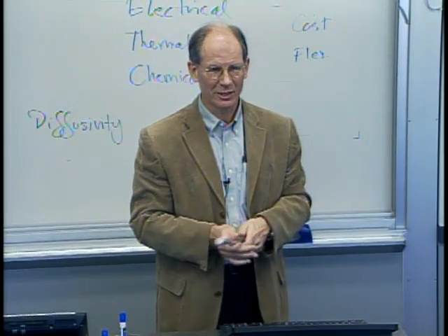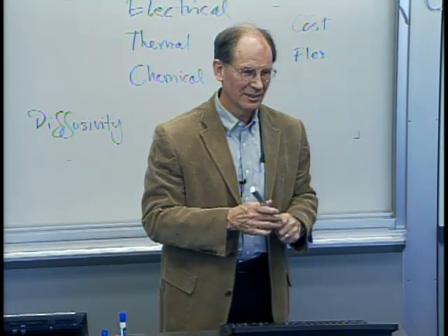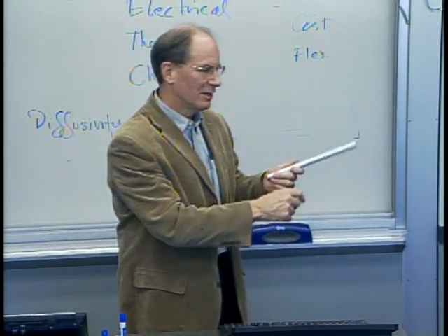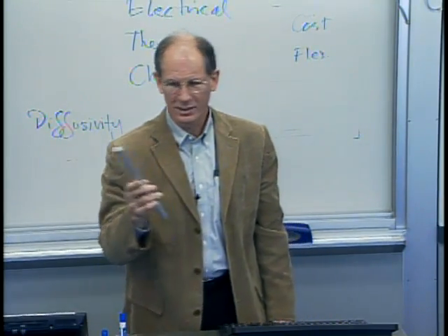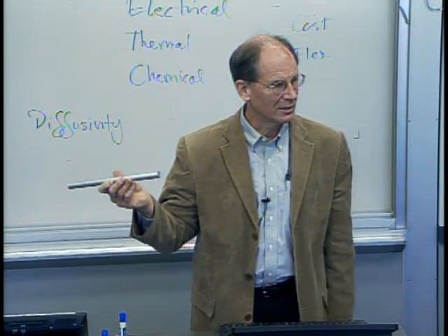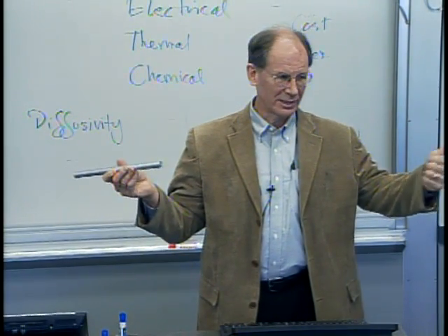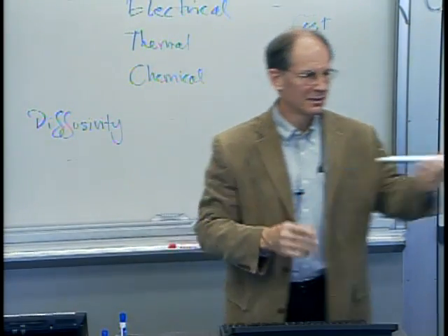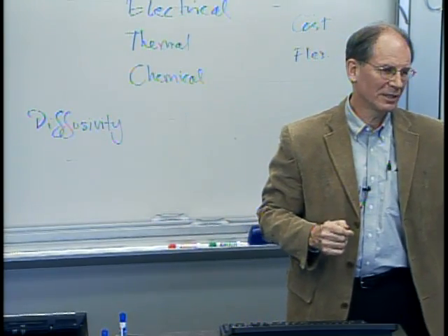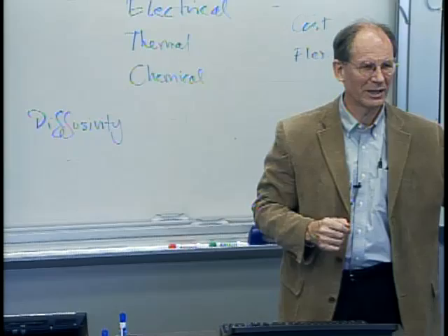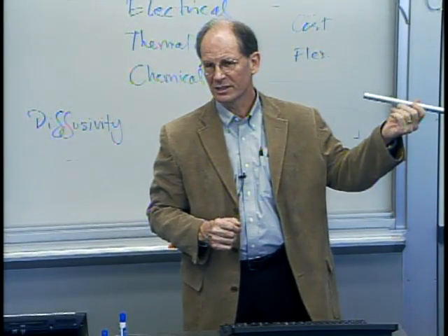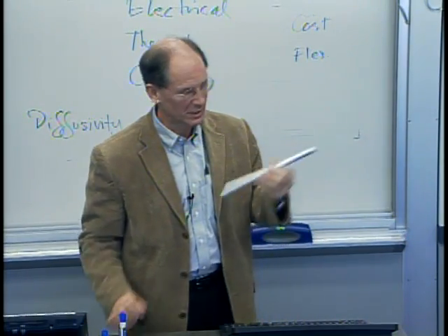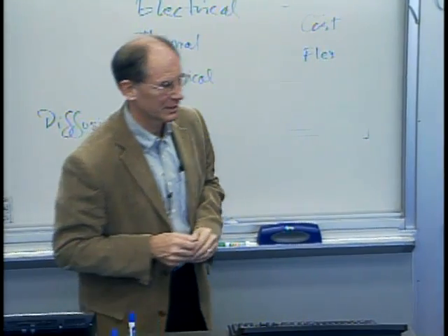Sure, if I put a different alloy in, or I sneak in steel or titanium instead of aluminum, yeah, that's a big mess up. But if I just say, well, here's a piece of aluminum, we did it in this mill over here, and it came out with the following properties: its elasticity, its yield strength, its strain hardening characteristics. And then I get supposedly the same material from a different mill, and they're 10% different. Not the elasticity, by the way, but all the others. 10% different. Huge difference here. Virtually no difference for the machining. So there's an inherent sensitivity of the processes to that.